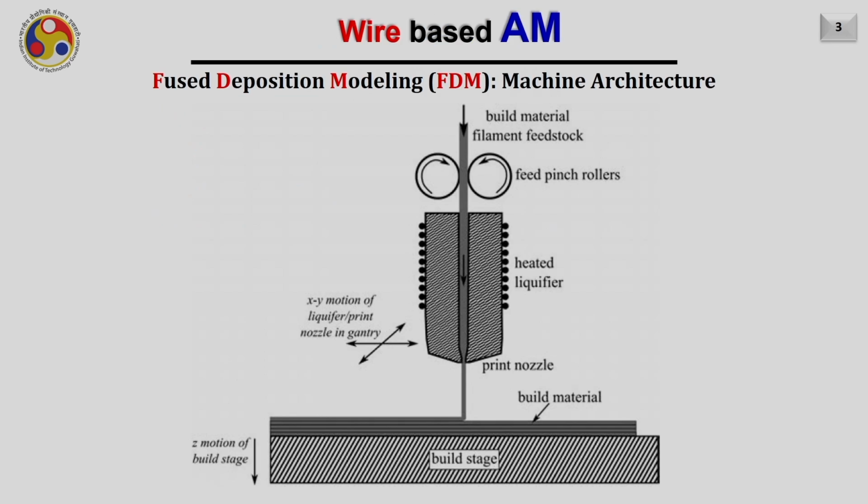So in the previous lecture, we have already discussed this region, which is primarily for feeding the wire into the liquefier, consisting of the pinch rollers. We have also seen what should be the value of omega r in order to obtain the desired velocity of the wire, and we have also discussed the two phenomena, wire crushing as well as slipping between the roller and wire.